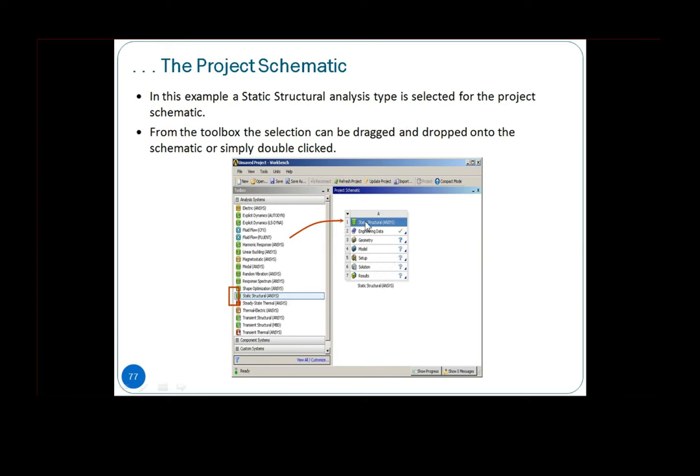So in the case of you want to share your results, let's say I'm performing thermal analysis, then I want the effect of the temperatures towards the structures, stress analysis, then probably you have to share your results. These two analyses have to be coupled. So meaning you have static analysis and you have thermal steady state analysis.